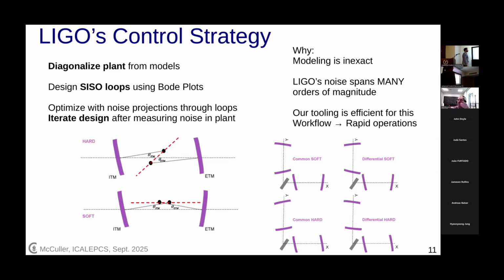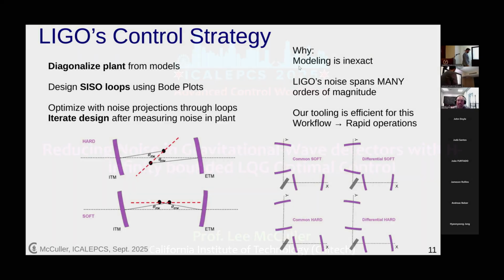And it just so happens that if you work through that, there's a basis where it is fully diagonal. And that's just a convenient thing, except that it's inexact, and it makes us have to have perfect output, actuator, and input sensing decoupling matrices. And that's just not true. We do not have perfect decoupling matrices. But if you assume that, it actually is otherwise perfectly diagonal, as a plant.